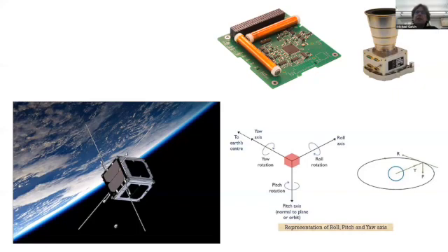But all of these things are used in combination, usually with a filter, often a Kalman filter, because you get all this different telemetry from the star tracker and the magnetometers, and you want to combine it all to figure out the most accurate pointing orientation that you can: where are you pointing, how fast are you rotating, and how fast is your rotation accelerating.